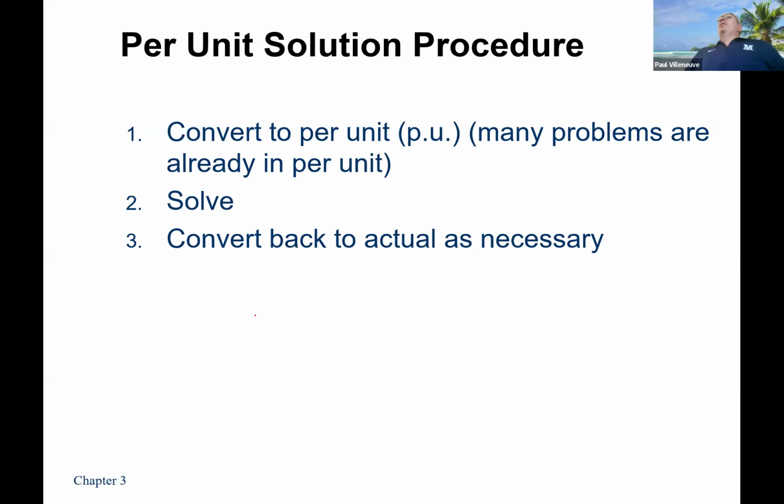So most of the time when we're analyzing the system, unless we're looking at things purely from an overload perspective, not a fault, we may want to look at the current, but oftentimes we look at it in terms of power. Are you moving more than, let's say, 2,000 megawatts through that new DC transmission line? If you're pushing 5,000 megawatts, okay, you've got a problem. Or what's more indicative is the voltage at one end of the line is 0.7 and the other end is 0.95. That's a huge voltage drop, which usually means you have some major problems in your system. So that's why we try to leave the data in per unit as much as we can.